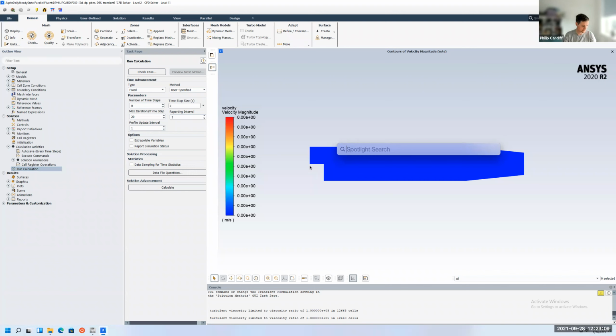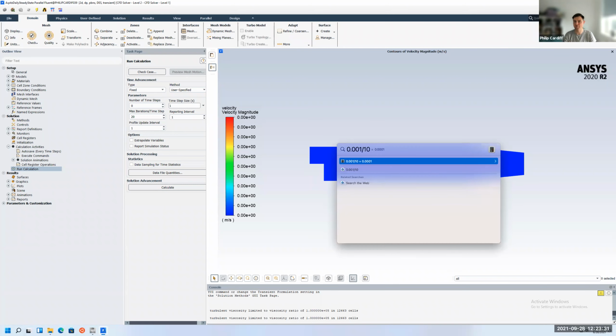The formula for the Courant number is the distance traveled by the flow over the cell size. So distance is the velocity times the time step, over the cell size. You can rearrange that to solve for what the time step would be. So if I take the cell size of 1 millimeter, this is just approximate, and I divide it by the incoming flow, or the maximum flow velocity I expect in the domain, that will say that a time step of 1e-4 seconds will give us a Courant number of 1. Typically the PISO method is only meant to be used with Courant numbers of less than 1, say a fraction of 1.